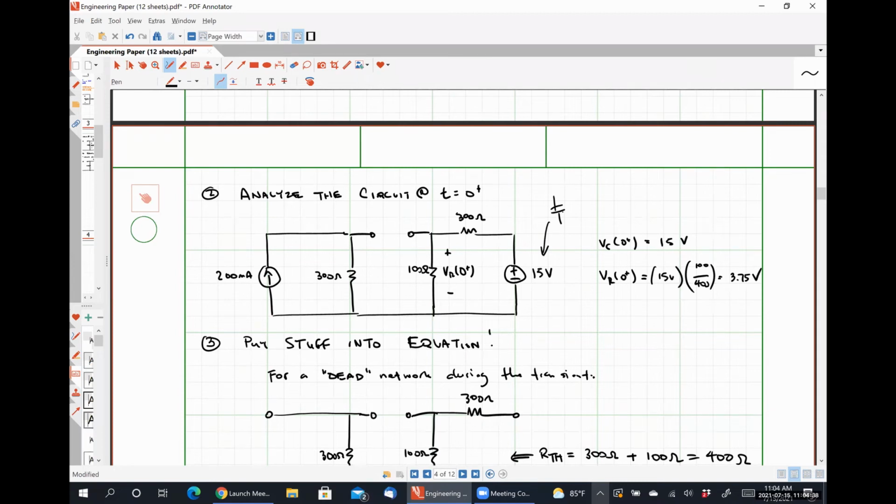So the Thevenin method that I just used is a more formal version of doing it by inspection. If you do the Thevenin method, you can't get it wrong unless you don't apply things correctly. But in the overwhelming majority of circuits that we're going to look at, you can do it by inspection. Okay, thank you. Any other questions?